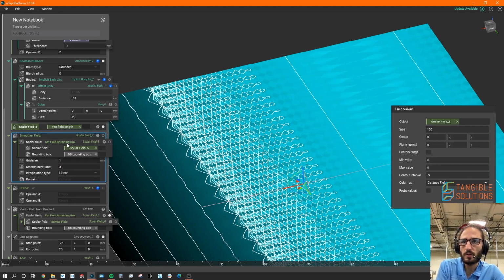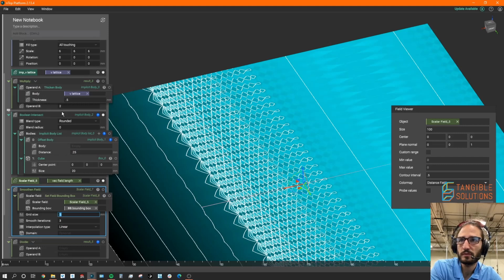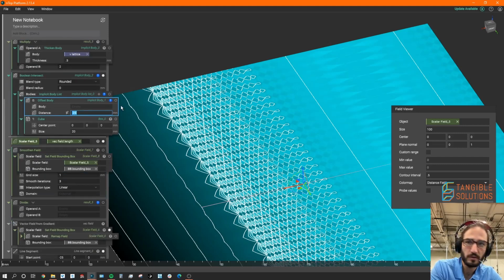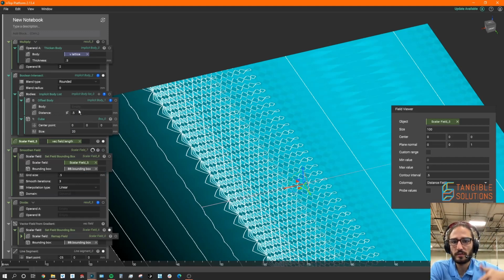If you're dealing with beam-based lattices, the grid size should be at least half of what your beam thickness is eventually going to be. That's just the rule of thumb that I use, not necessarily anything official. So up here, for my offset value on the offset body, we'll make that 0.5. We'll match the grid size to 0.5, since I'm offsetting bidirectionally from the non-dimensional beam, so the offset will be a millimeter total thickness.